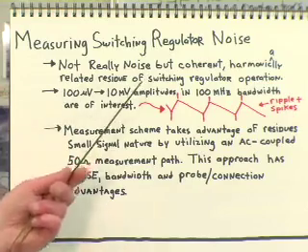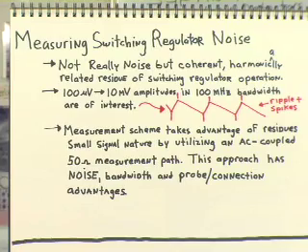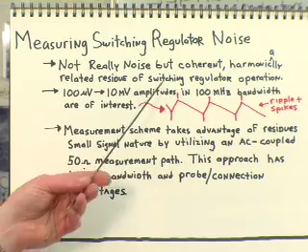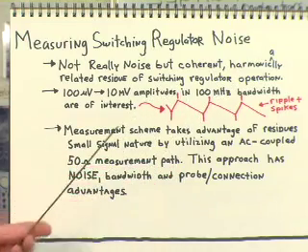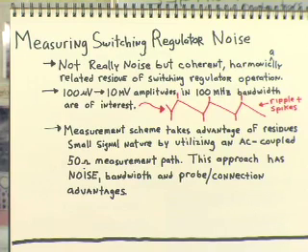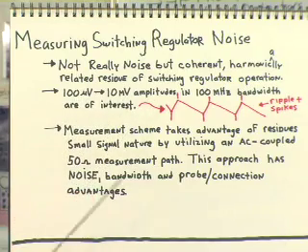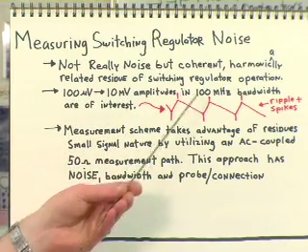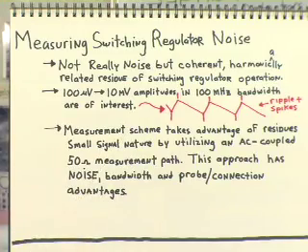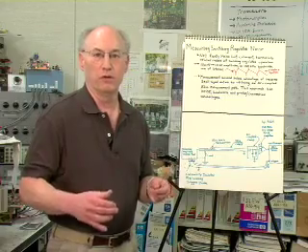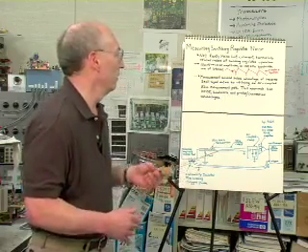We're not really measuring noise at all. Noise is randomly occurring events. We're measuring coherent, harmonically related residue of switching regulator operation. It's directly related to the switch frequency and the harmonics of the switch frequency. Typically, 100 microvolt to 10 millivolt amplitudes are of interest in 100 megahertz bandwidth. Why 100 megahertz? Because the systems you're building are sensitive to wideband operation.